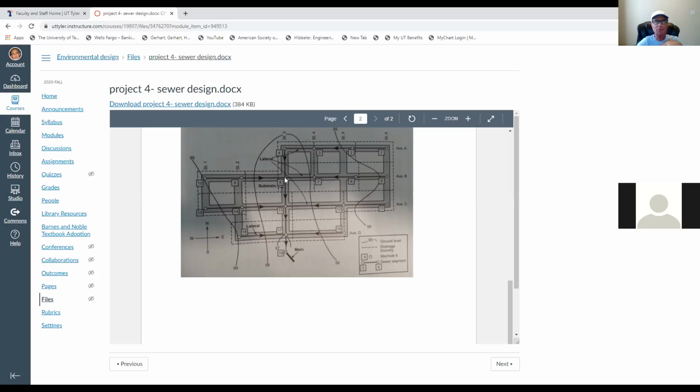At manhole 8, you add everything that comes from this side of Avenue B, plus what comes from Avenue B from the other side. This runs in this segment until you get to 13. At 13, you have the lateral from Avenue C from this side and Avenue C from the other side, and everything runs in this segment. At 17, you have what comes from Avenue D from both sides, and everything runs now to the 19 here. Make sense? That's the layout of this community.